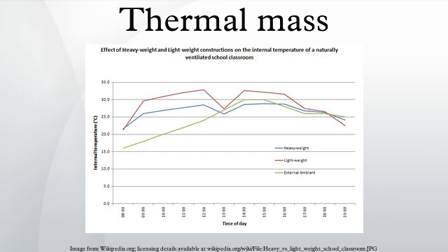Thermal mass in buildings. Thermal mass is effective in improving building comfort in any place that experiences these types of daily temperature fluctuations, both in winter as well as in summer. When used well and combined with passive solar design, thermal mass can play an important role in major reductions to energy use in active heating and cooling systems.